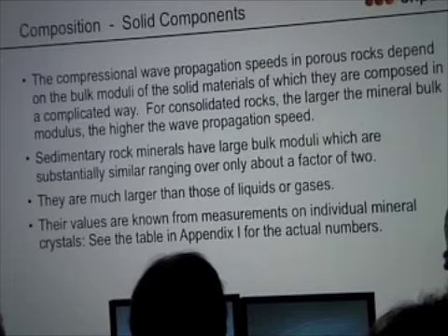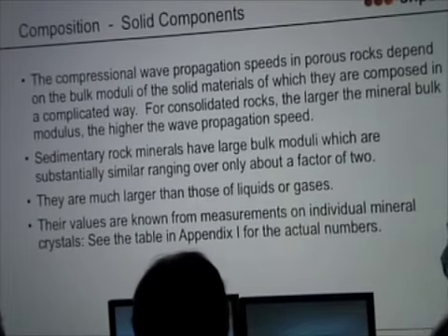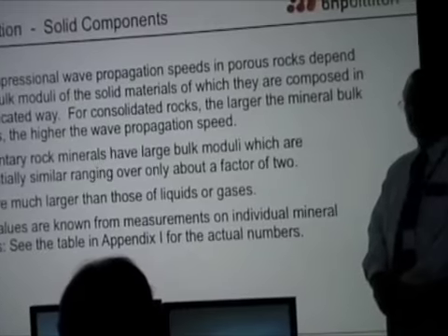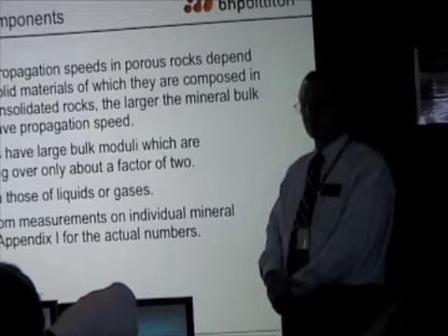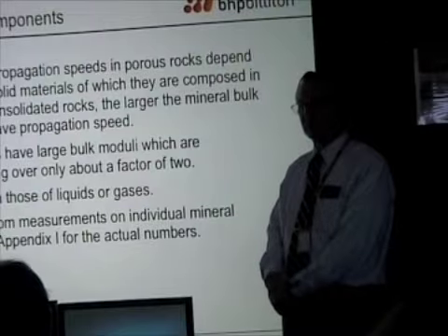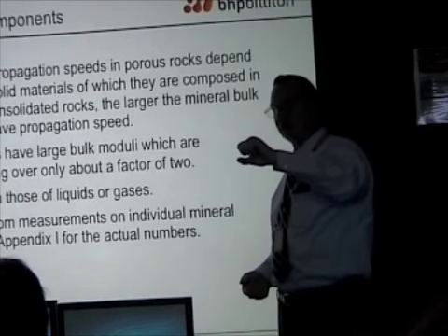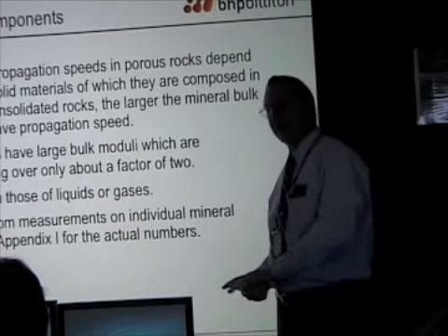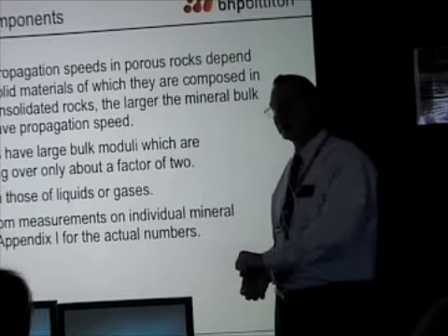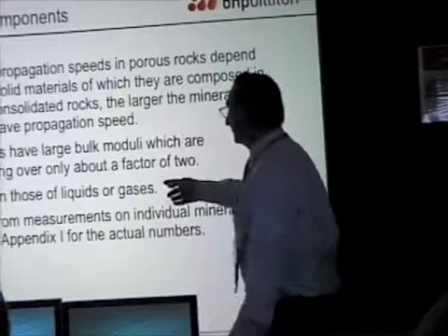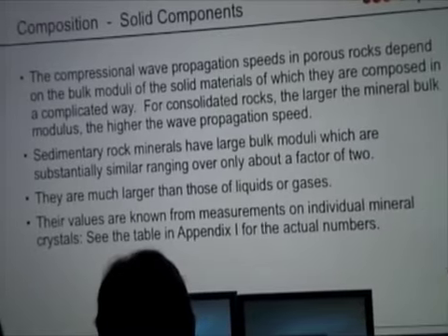And for gas, even gas at reservoir pressures and temperatures, typically 7,000 or 8,000 feet, let's say methane, something like 500 psi will produce the same 1% change in the volume. So solids are really stiff springs, fluids are less stiff, and gases, even at high pressure, are really pretty weak. Okay, the values are known. That's what that table's about. Thank you, Mike.